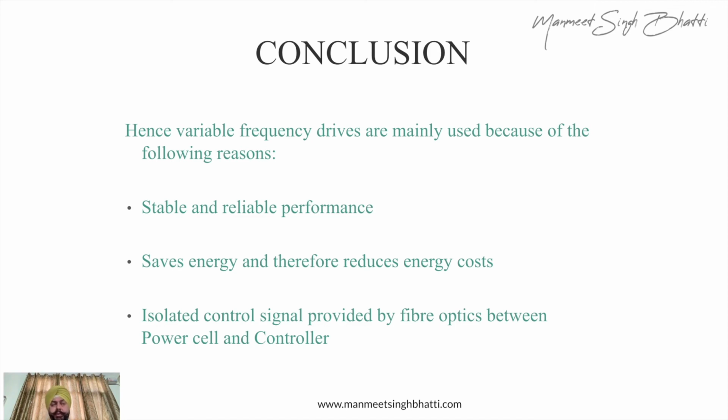Once you put a VFD in between, the VFD becomes a kind of protecting device also, because it's controlling the power. So if anything goes wrong, it happens to the VFD. It never gets passed on to your motors. So your motors, which are bigger and costlier, don't have to bear the brunt of the power quality. Most of the quality issues in the power are taken care of by the VFD. So the VFD gives your motor the required quality of power.